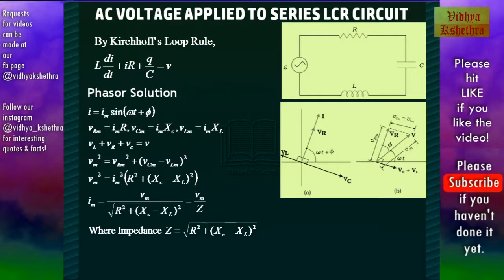Now looking at figure B, by using Pythagoras theorem, we can write Vm square is equal to VRm square plus (VCm minus VLm) the whole square. That is, substituting the values, Vm square is equal to Im square into R square plus (XC minus XL) the whole square.